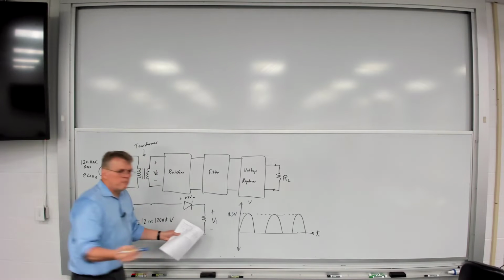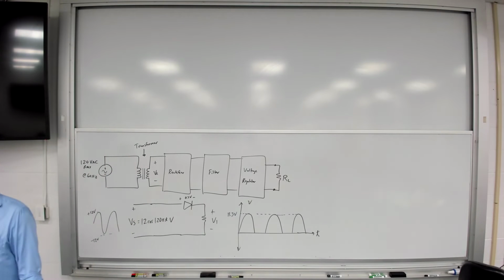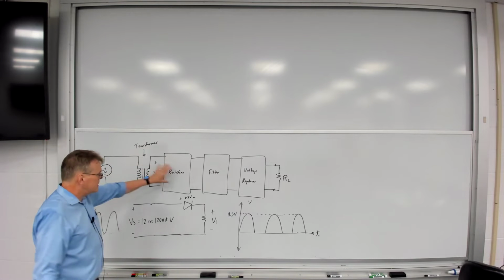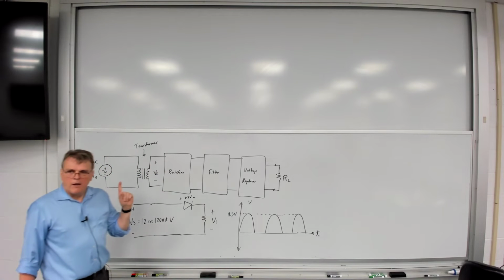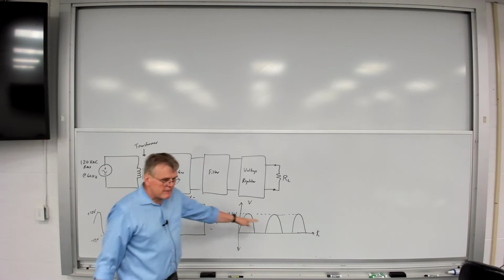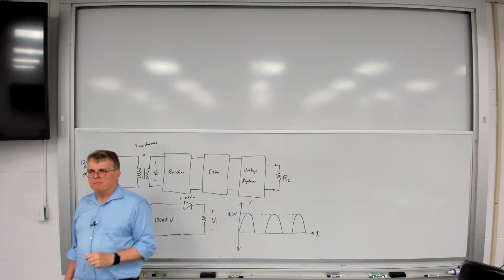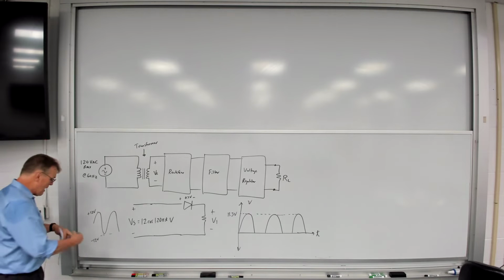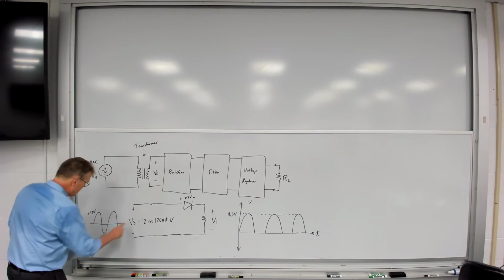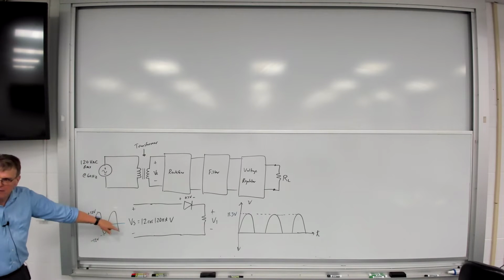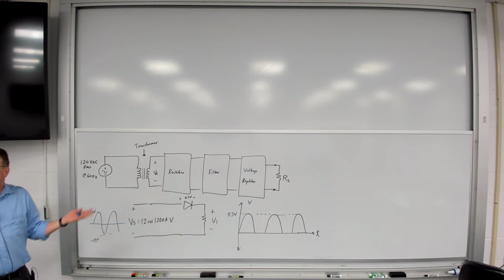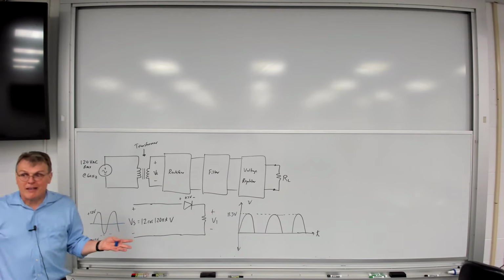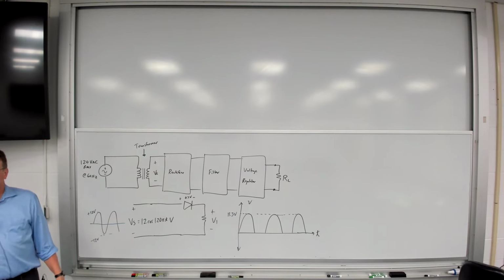So this is a basic half-wave rectifier. That's the first step of converting AC to DC. But you know, there's something fundamentally wasteful about the half-wave rectifier. And that's the fact that you are throwing away the negative half of the input waveform. We just block it. We don't use it. But that's, in effect, available energy that we're not using.